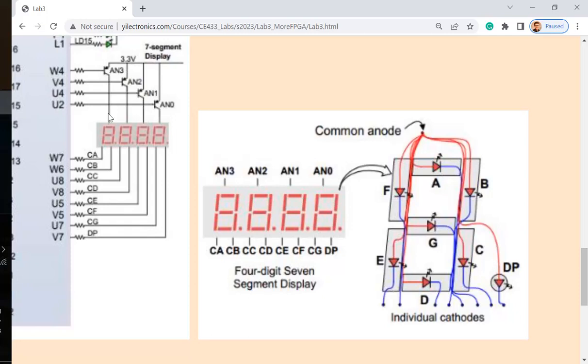Are these one here, one here, one here, one here? Are these 4 wires connected to the common anodes of each digit? So what are these lines? What are these ones connected to? Here, here, here, here. They are shorted to where? To the common anode for each digit. But they are individual, they are not shorted together, you can tell. You need to individually control them, right?